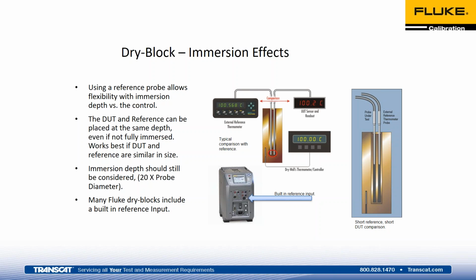So if you look to the far right, I have an example of how to use a dry well with a reference where they both, again, are not fully immersed. At this point, the display setting of the heat source, or your dry well, just becomes a nominal set point, and then your reference would be true temperature, and then you would take your data from the device under test.